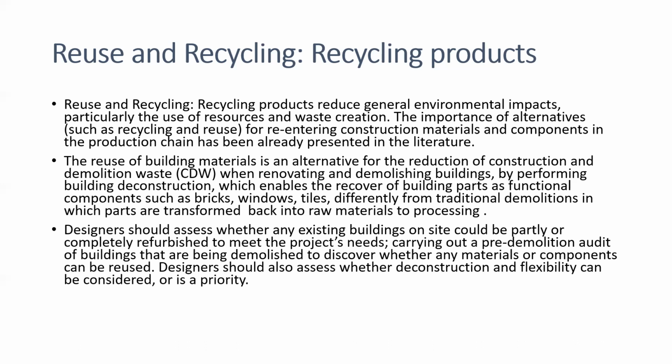Designers should assess whether any existing buildings on site could be partly or completely refurbished in order to meet the project's need. Carrying out a pre-demolition audit of buildings that are being demolished to discover whether any materials or components can be reused is also important. Designers should also assess whether deconstruction and flexibility can be considered, or whether it is a priority.